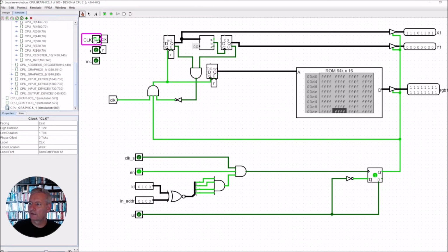So that goes to the value F, 1, 2, 3, 4, 5, 6, B, C, D, E, F. So this is FF, and when the next clock pulse comes along, it goes to 0. This line goes to 0, does the comparison, it's equal, so this line here will start counting. You can see the Y value is going to 1. So we've put in the first 256, and now the Y value has gone to a value of 1.